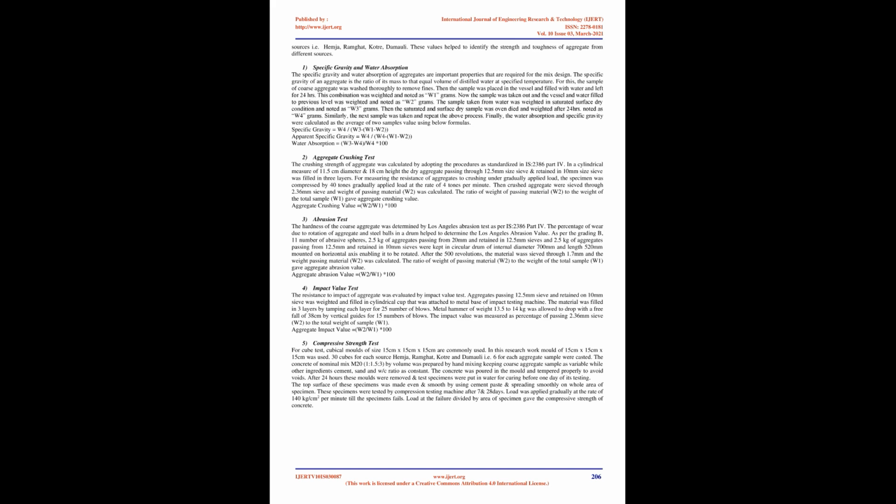Coarse aggregate: in this study coarse aggregate was collected from the 4 different locations along the length of Seti River as shown in table below. Water: the potable fresh water available in the lab was used. The water-cement ratio used was 0.5.